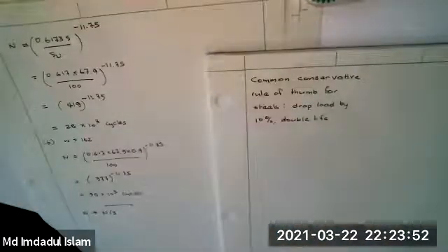Drop the load by 10%, you double life. So if you drop it twice, 2 times by 10%, you get 4 times the life.